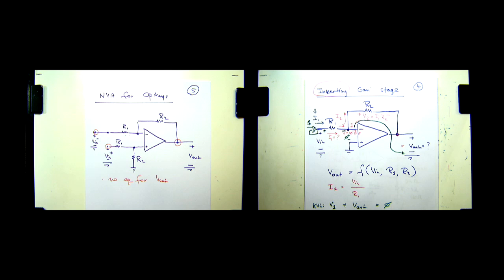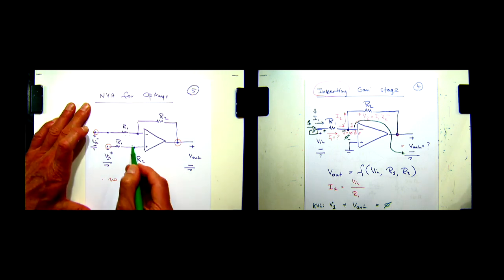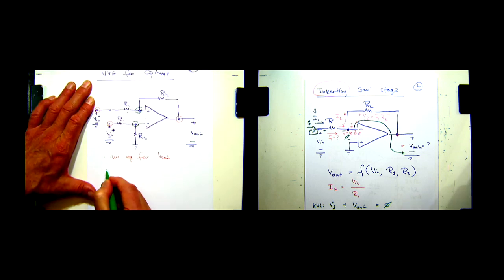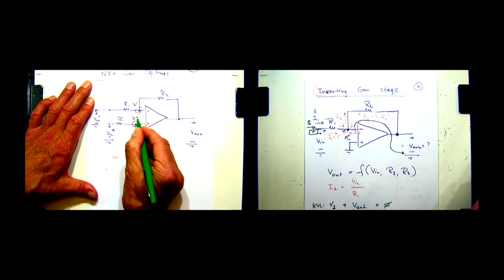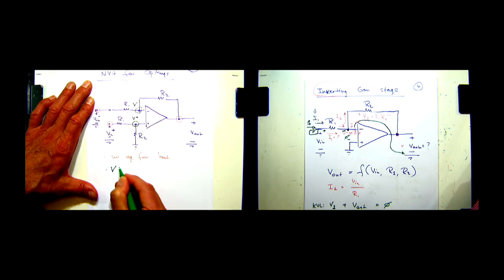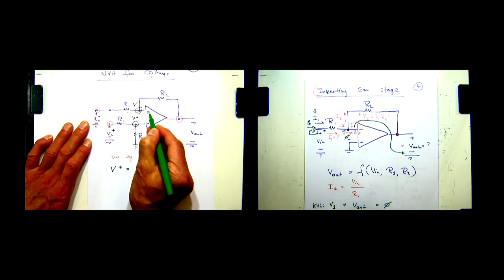And then all the other nodes we have to write equations. So in this particular case there are 2 more nodes, this one and this one. We have to write equations for those. And then further, let's call this V minus and this V plus. Further, we have a new equation that we normally don't have. We have that only with an op-amp: V plus equals V minus. Right? Ideal op-amp. Oh, and just be sure, don't forget to check we have negative feedback. Yes. Okay?